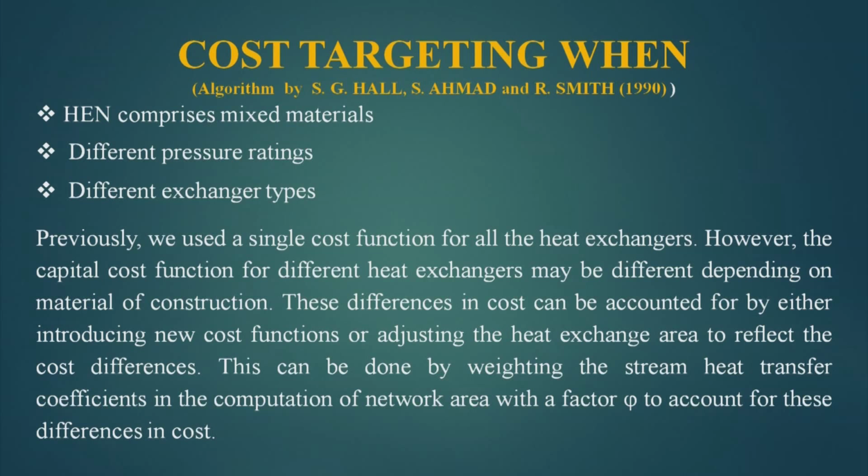The concept is simple, that for each heat exchanger in the heat exchanger network, either we use different cost functions for computing that cost, or we artificially or virtually increase or decrease the area of the heat exchanger present in the heat exchanger network to accommodate the cost change, which will be there due to the difference in material, difference in pressure or difference in exchanger type.